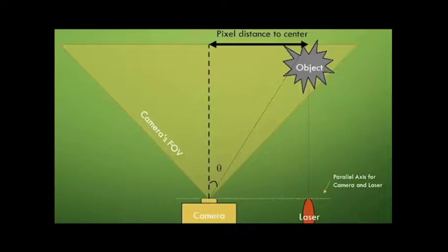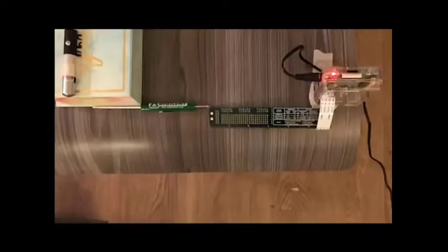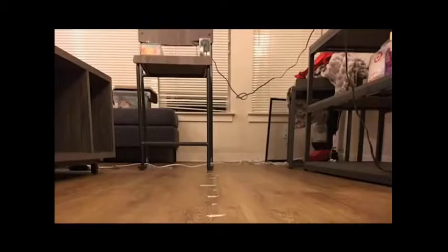For both a point and line laser, the camera field of view widens as the distance increases, so the laser appears closer to the center at further distances. Theta was determined by calculating the number of pixels to the center of the image, multiplying by the radians per pixel, and adding a radian offset. The radians per pixel and radian offset were both experimentally determined in calibration. For both the point and line laser, a 6-inch increment was used for the calibration and range curve.